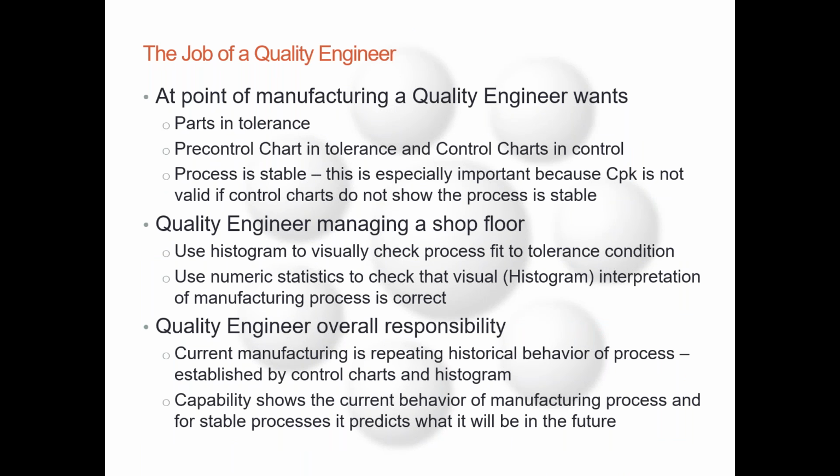The job of a quality engineer, at the point of manufacture, is to know the parts are in tolerance. That's our pre-control chart. The pre-control chart is in tolerance, and the control chart is in control. So the control chart is now taking a step back from what you see on the pre-control. The pre-control is really details of what's happening right this minute. The control chart's looking at it over a longer range.